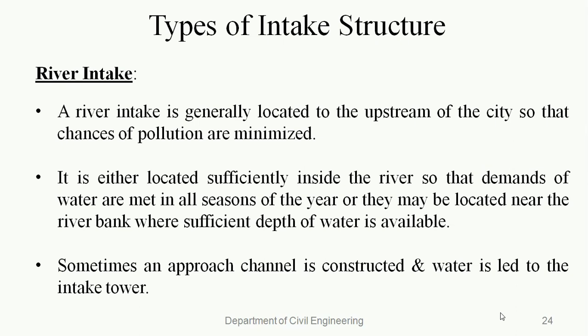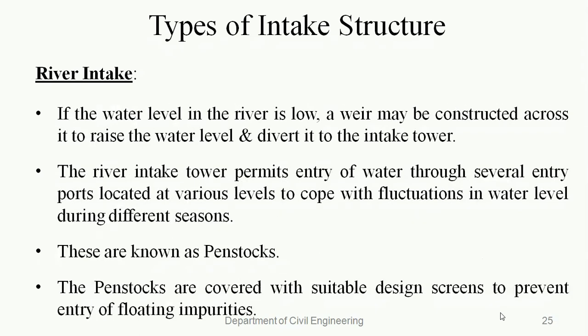In a few cases, an approach channel is constructed and water is led to the intake tower. If the level of water in the river is low, a weir may be constructed across the river to raise the water level and divert it to the intake tower.